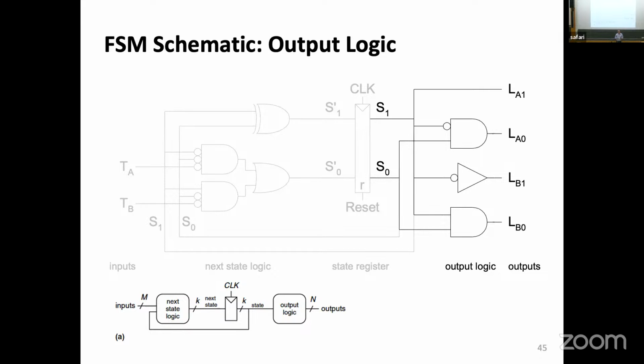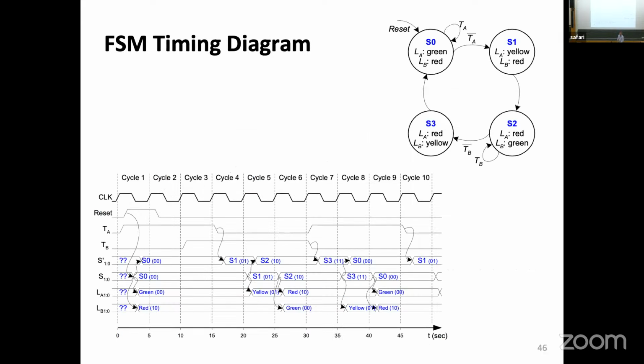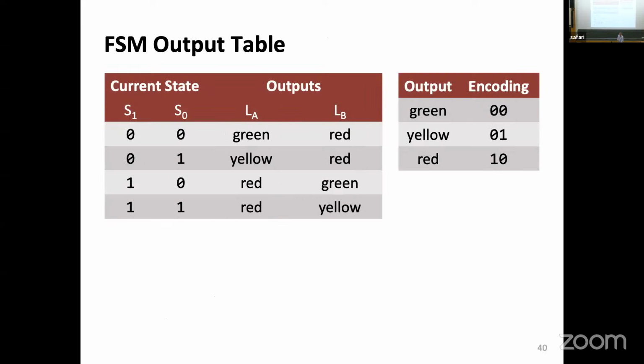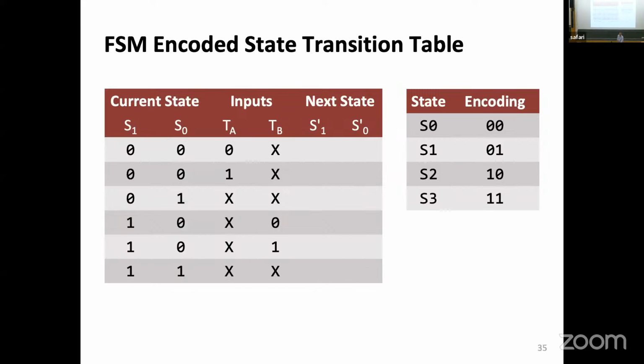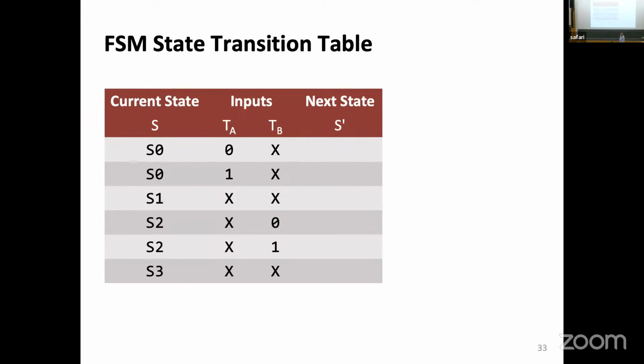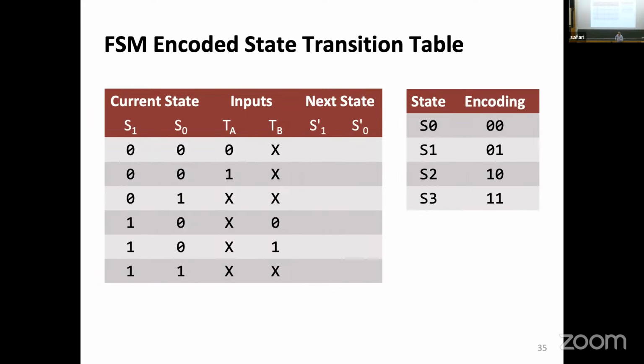Now, there's a lot of arbitrary decisions that were taken here. And they would have affected the results if you're doing this on your own. The first decision that we have taken is how I call these states. You know, is this state 0, is this state 1, or whatever. The next thing also related is how I encode them. Nobody says that S0 should have been 0, 0. It could have been 1, 1.